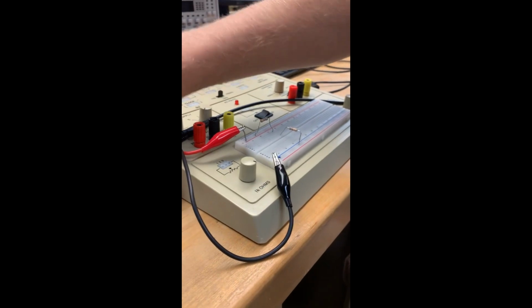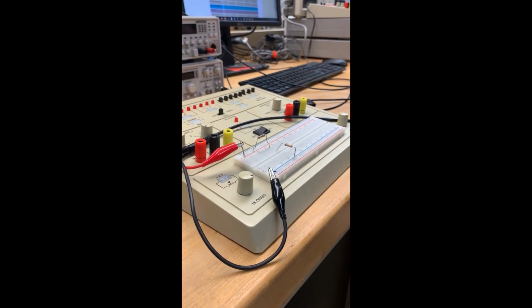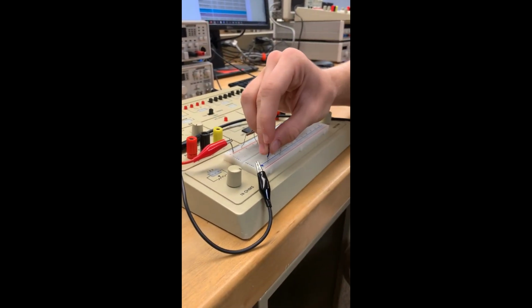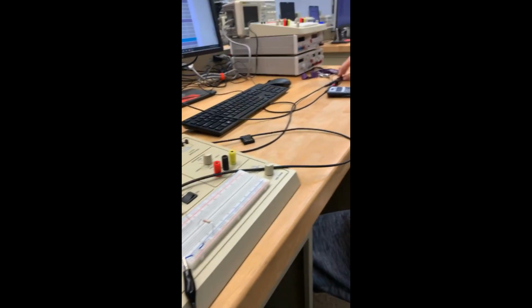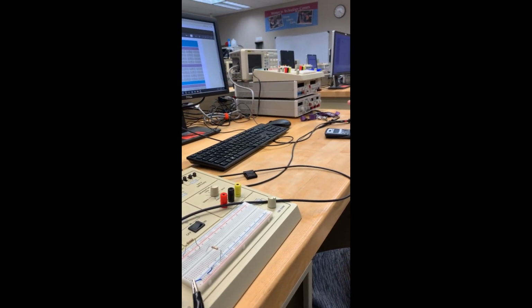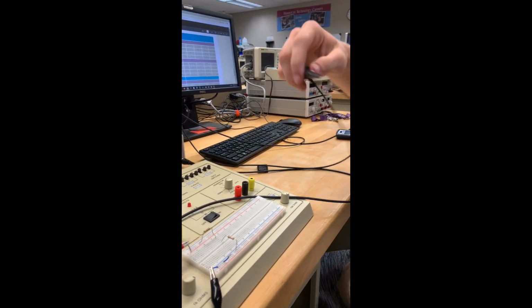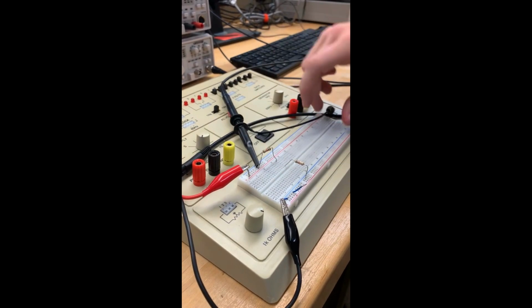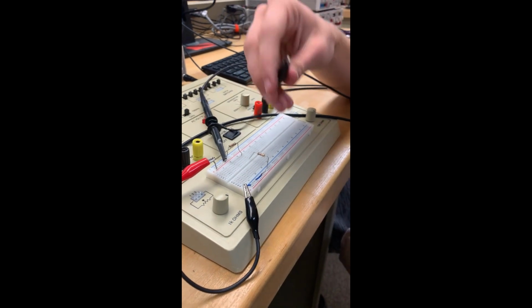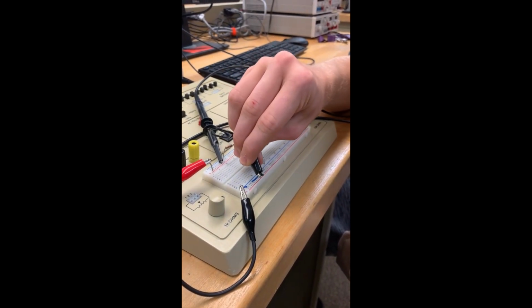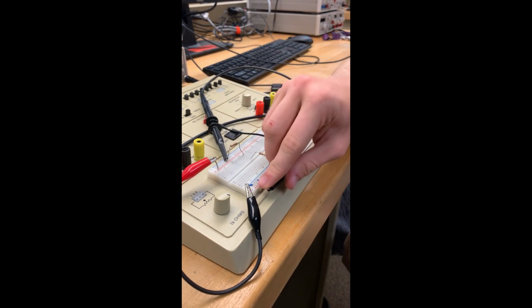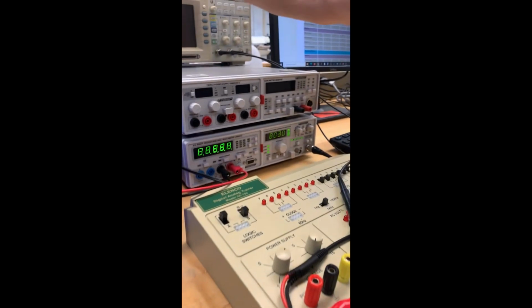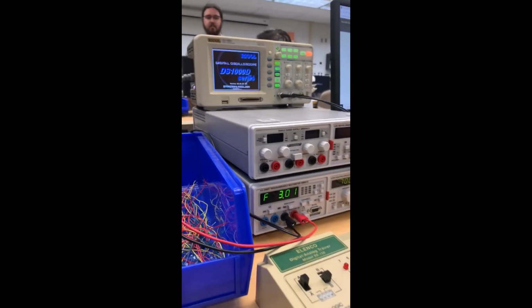And now our circuit is ready, and we need to connect our oscilloscope to measure. So we're going to get our oscilloscope. We're going to put one side on the same area as in Multisim, at the start of resistor 1, and the other side will go into ground, as it is in Multisim. And now we turn all of our tools on.